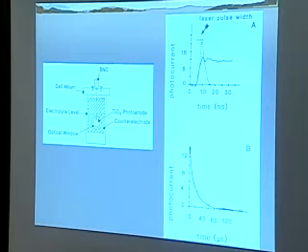And even if you had a faster pulse, it wouldn't really matter because you have an RC time constant, which you don't have in normal photochemistry, and you're not going to go any faster than the cell's RC time constant, and that's going to be more on the microsecond time scale no matter what you do. So that's the first complication. The second complication is you have essentially a big noise problem. That is, you're looking for a small signal that's time varying over a fairly short time, and you don't have a clean way of getting at that signal.